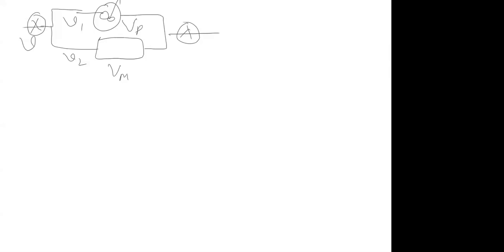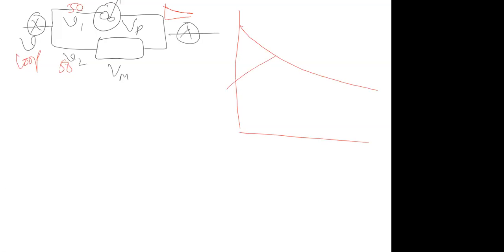So imagine you injected, let's say, 100 particles here. Depending upon the flow rate, they will split. Let's say 50 go here and 50 go here. The 50 which go here will appear like this. So at the outlet, you will get this kind of CSTR RTD. What is the area under the curve? How many particles? The area under the curve corresponds to 50 particles.